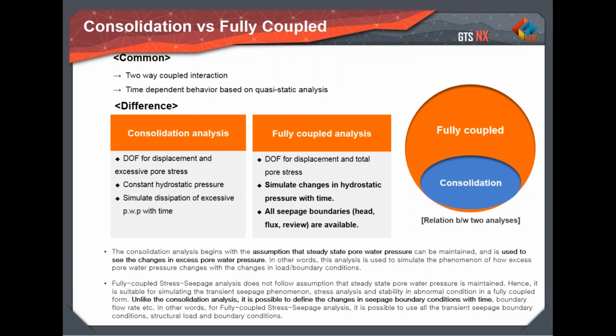For example, in Mexico City, they built the city above a lake bed, and there are higher concentrations of pore pressure at different depths of layers. So that cannot be captured fully by just defining a constant hydrostatic pressure. You have to use these kind of advanced seepage boundary conditions, manually defining pressures at different layers to capture that. But the idea being that the program does allow you to do that, and the fully coupled analysis is how you go about it.